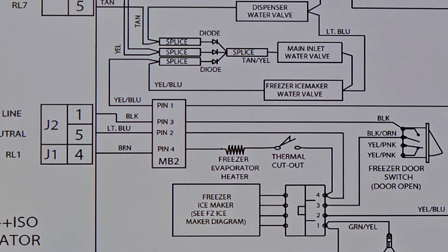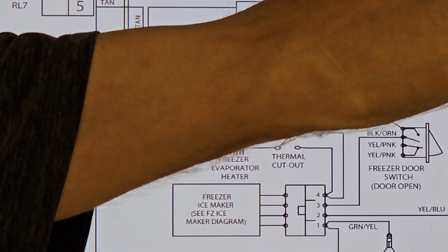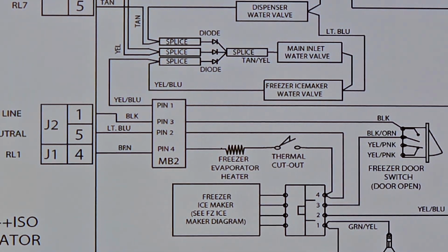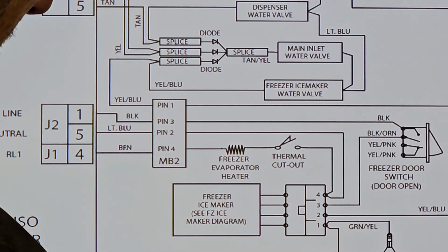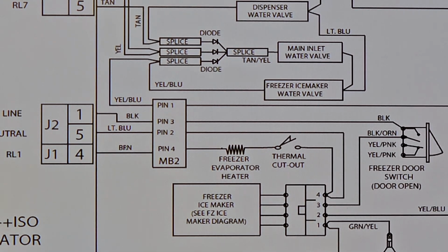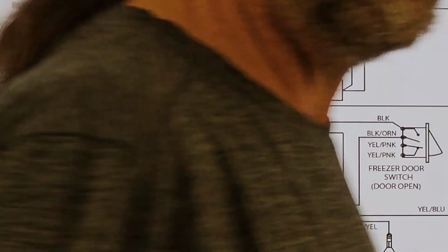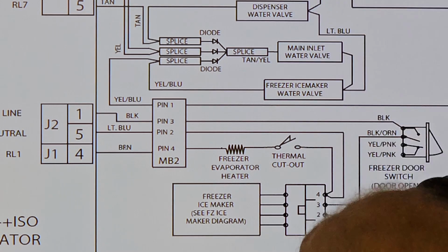Yes. So in this compartment, when you look all the way in the back, after you take the bucket out, there's a fan back there. And not only is there a fan back there, but there's an evaporator behind it. Okay? So that evaporator is controlled by here. Ice maker, evaporator, and defrost bimetal. If I have a defrosting problem in the ice maker compartment, would that cause the compartment to get warmer and then not drop ice? Yeah, because if it doesn't defrost, it'll make the compartment warmer or lose air circulation.